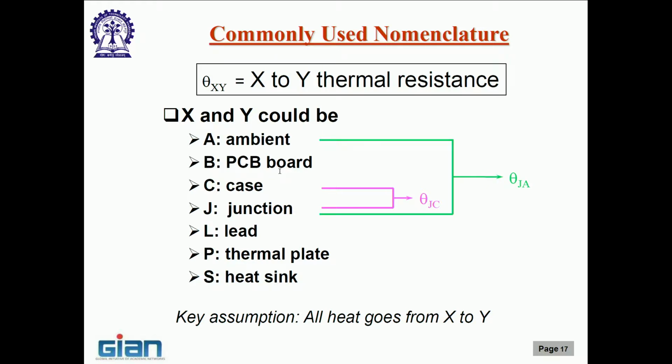J is the junction. This typically is an internal temperature inside the die, inside the silicon. Okay. So, inside each transistor or inside the normal die? Good question. Typically the maximum temperature; there can be multiple junctions. If you select a multi-core architecture, you have multiple junctions. So it depends on the hottest temperature that we try to design for, and we call that the TJ.